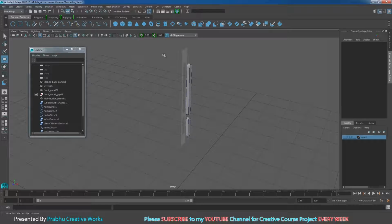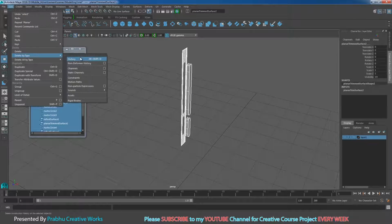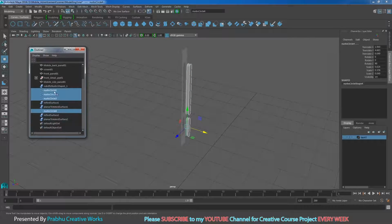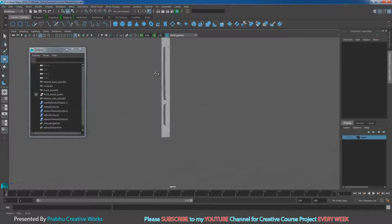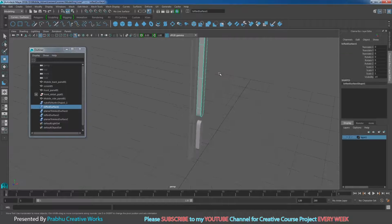Now I select all the objects over here, go to edit, delete by type and choose history. Select all the nurbs circles in your scene using Control, press delete on the keyboard. That means all the nurbs circles will be gone. So I will select this object.